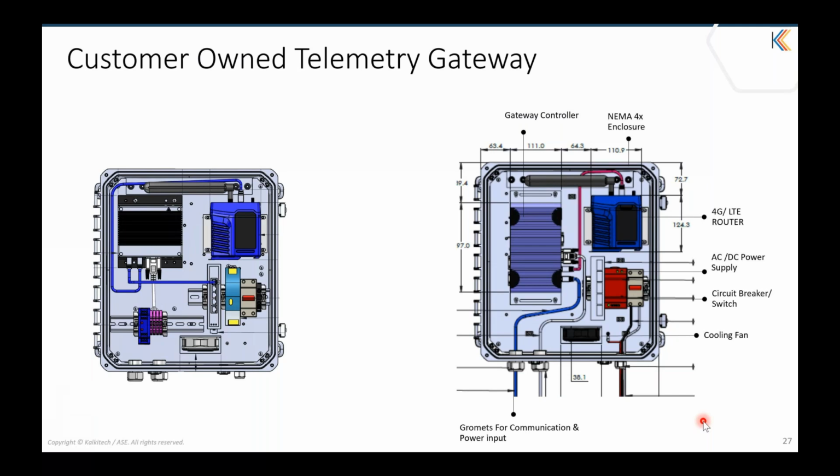Again, the gateways or aggregators provide direct integration with the assets in the field, and as per the utility requirement, this data can be integrated with the utility systems directly or via the utility-defined protocol. In California, it's 2030.5, and the same aggregator can also be used to integrate with the market applications for the day-ahead or maybe an ancillary market.